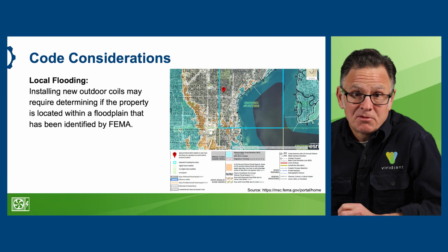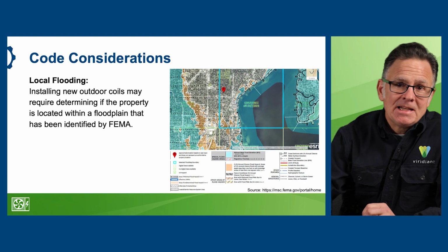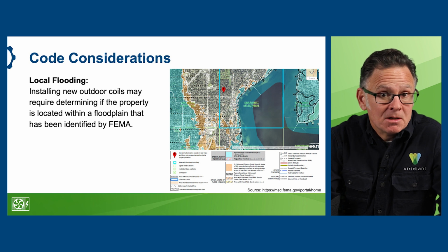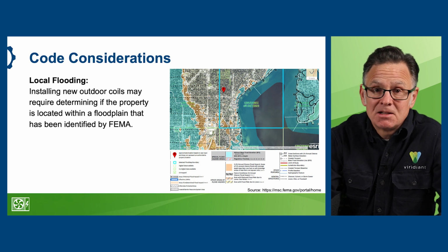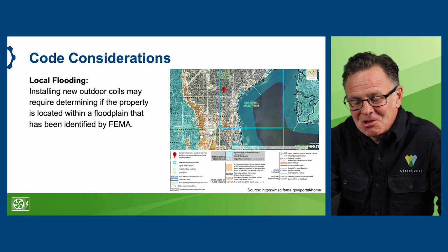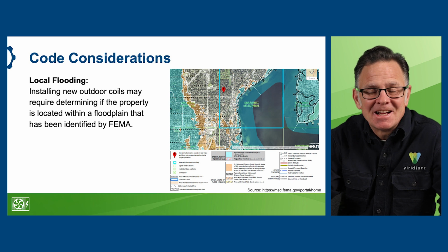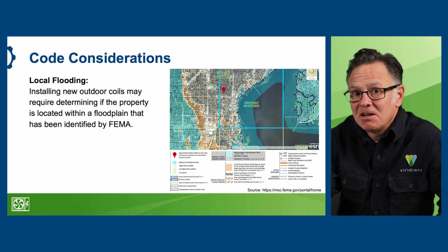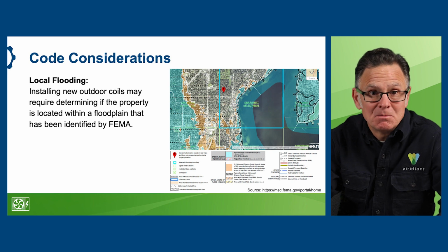There are, in fact, fewer code requirements that relate to heat pumps compared to a fossil fuel system because you're not installing a combustible gas. You don't have to worry about providing combustion air, and you don't have to worry about venting fumes.